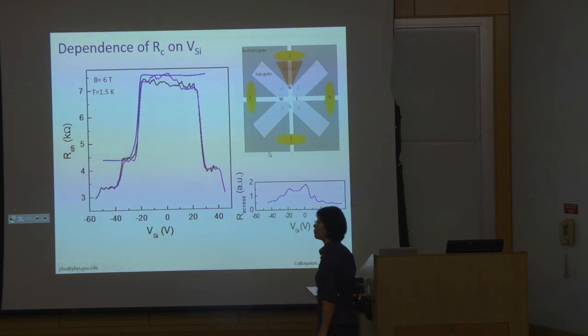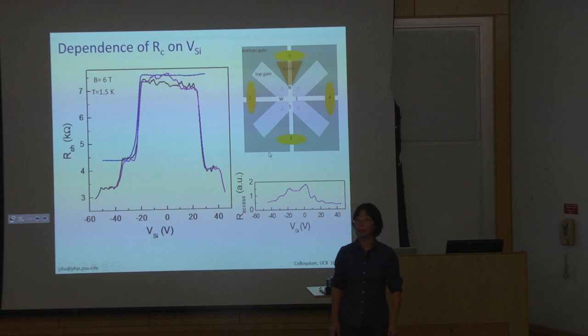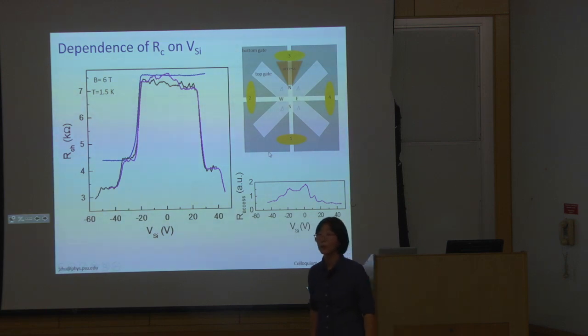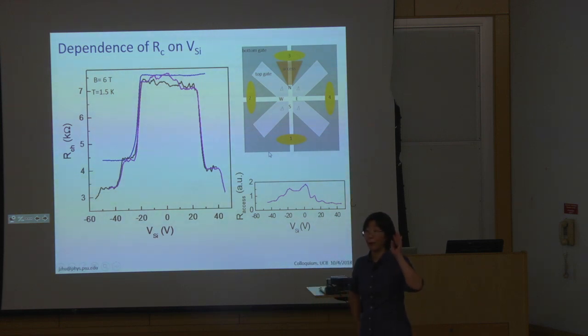Maybe one more question? Yes, you started by promising conductance without resistance. Now, these wires have 6 kilo-ohms, and there is no way this is real dissipative resistance, even though these are ballistic conductors. So where is the source of dissipation? This is what I claimed very honestly from the beginning, that my ballistic wires have quantized conductance. They're not superconductors. So the dissipation happens at the contacts. The voltage drops at the contacts when you enter or exit.